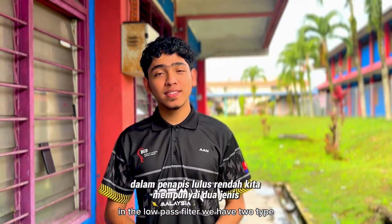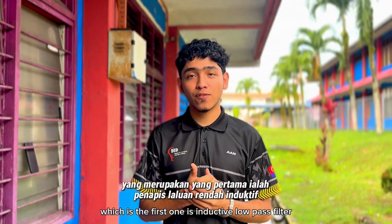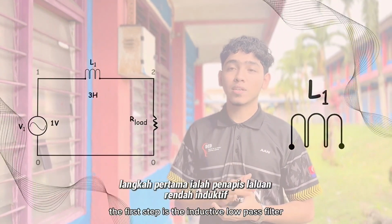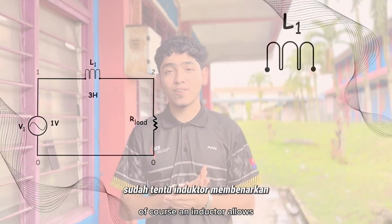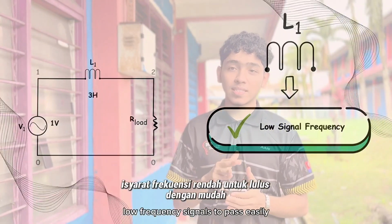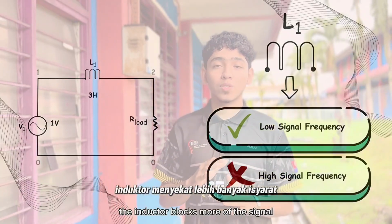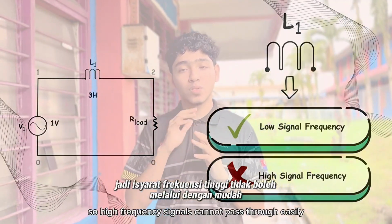In the low pass filter, we have 2 types. The first one is the inductive low pass filter, the second one is the capacitive low pass filter. The first type is the inductive low pass filter. This filter uses an inductor, of course. An inductor allows low frequency signals to pass easily, but when the frequency becomes high, the inductor blocks more of the signal, so high frequency signals cannot pass through easily.